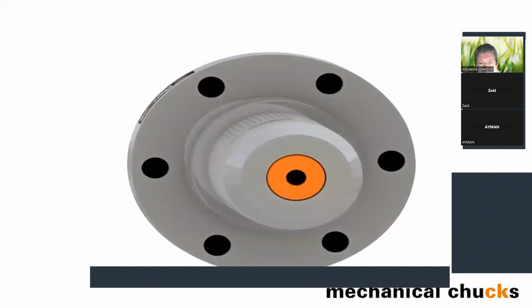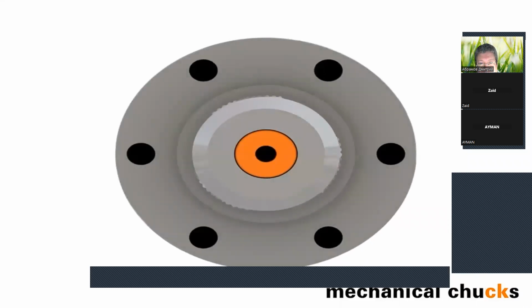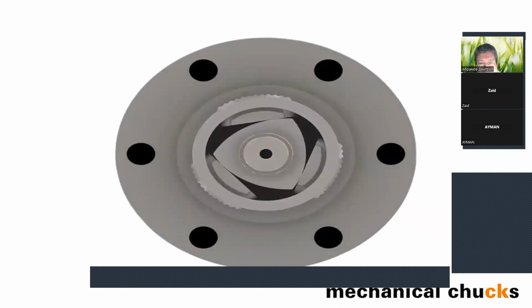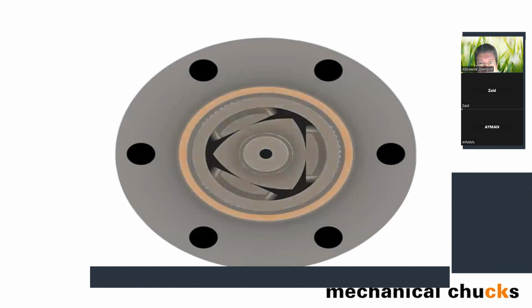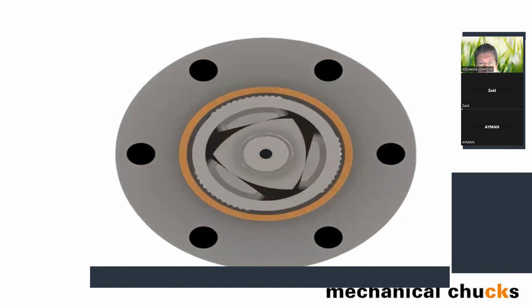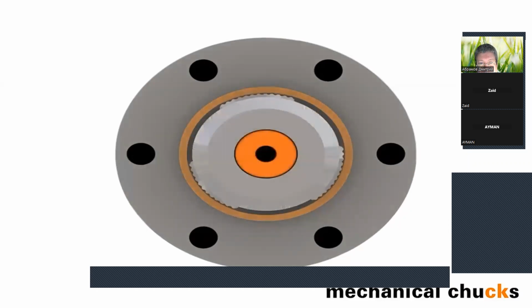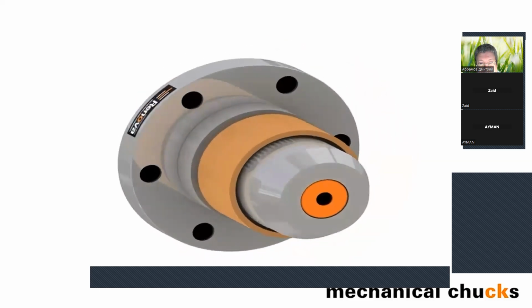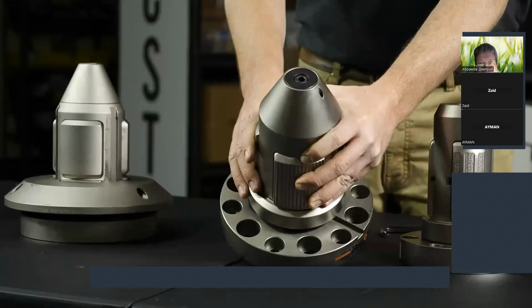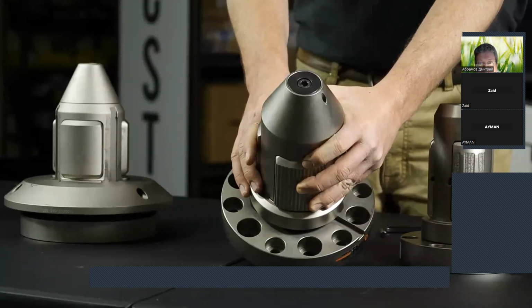Our chucks are designed for American cores. That means that our 4-inch chuck is a 4-inch chuck and not a 100mm chuck. A 100mm chuck is only 3.94 inches. That may not seem like a big difference in size, but when you have a chuck that has a snugger fit to the core from the beginning, you're able to get full engagement faster and increase your splicing speed without sacrificing web tension.